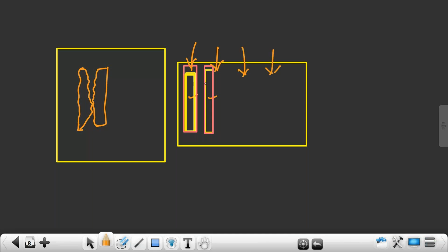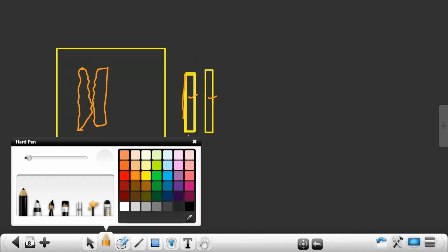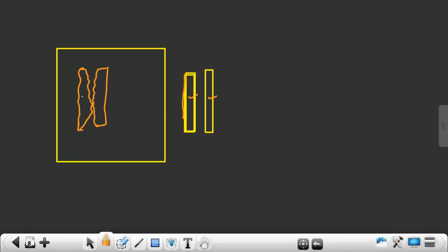But this region is not treated with acid because it is covered through what? Mask. We already covered it. But the remaining regions we treat with acid, and the remaining regions are removed. Then I will get the metal layer only in this region. Do you think that when I treat this entire region with acid, I can get this planar structure? No, I will not get a planar structure. I will get a structure like this. So without our notice, both the metals are what? Shorted. And this IC cannot work.